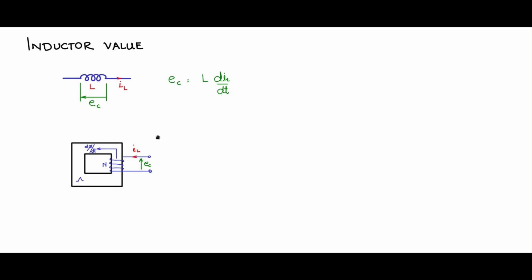Now, with respect to such a physical fabricated inductor, what is the value of L, or how is L related to these core parameters and physical parameters? So let us go back to the fundamental equation. Phi is equal to permeance into MMF. Recall, as a comparison, you can jog your memory using charge Q is equal to CV. Flux phi is equivalent to charge Q, permeance is equivalent to C, MMF is equivalent to the potential, and that is what this equation is.